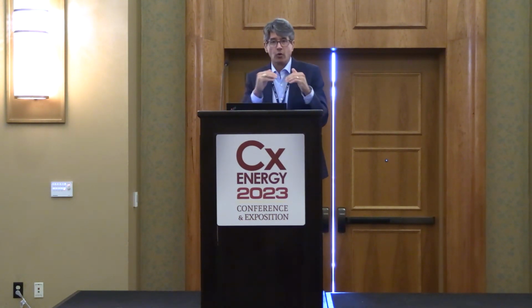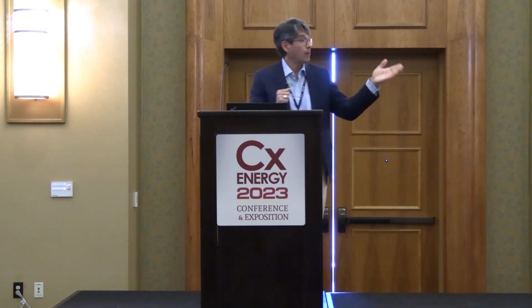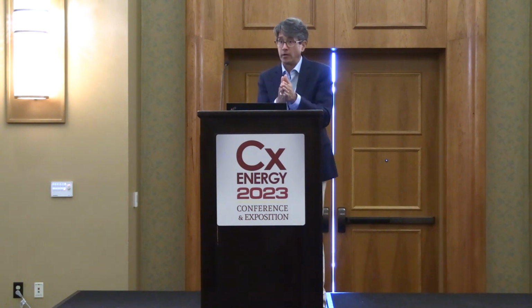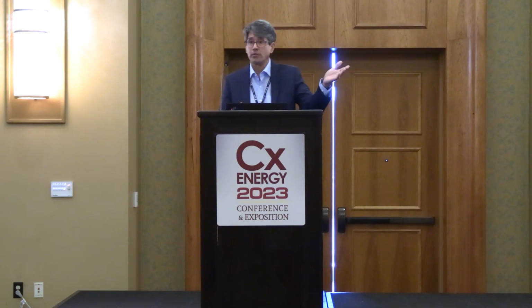So you've got to think also of how that equipment is controlling, thinking that in your tolerances. A lot of people say, I have a lab or an OR. I've got an environment, I need tight tolerances. Think about it, a lot of times in labs and ORs, air changes per hour is going to dictate your air volume as well as your room pressure. So if you have a tight room, you're going to have to start making some adjustments to your exhaust, your outdoor, or your supply air to maintain that pressure. And now all of a sudden one of those is probably going to be more than 10% out, or if your room is too loose. So that can dictate you not being in tolerance of airflow.